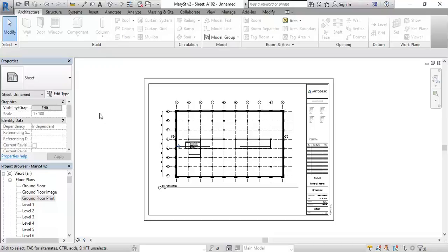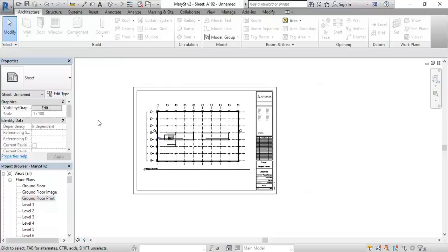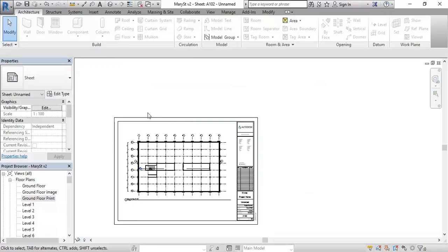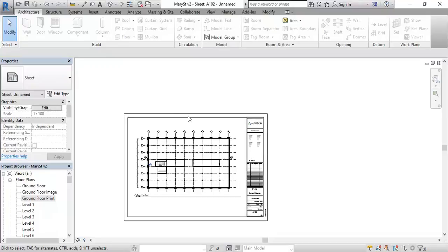Yeah, that's right. And that's often the case. We do end up with bigger sheets and bigger format because of that. You need to show more detail than in, say, an architectural presentation. So that's not unusual. And I think the most appropriate for this would be AO sheets with the plans at 1 to 100. That gives you the potential to have a nice layout because you can have room around your plan to maybe get other views, perspectives, and section views. And then also you need annotation, diagrammatic elements, and all those other things that you should have in a final year presentation.